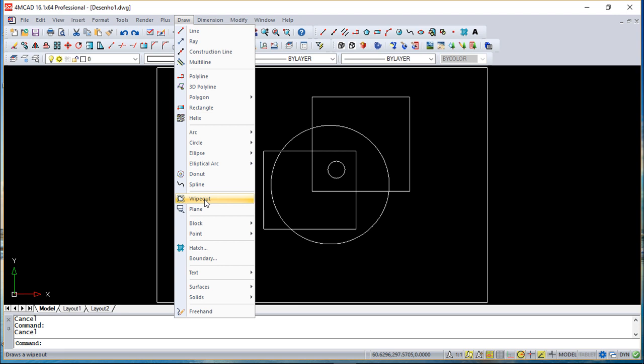We are creating something, and these entities can help you to hide areas of your drawing. They display the current background, so you think you are making part of your drawing invisible, but in fact you are creating an entity that is covering what you have behind. But this characteristic is to have the same color as the background, so it seems that you are hiding something.